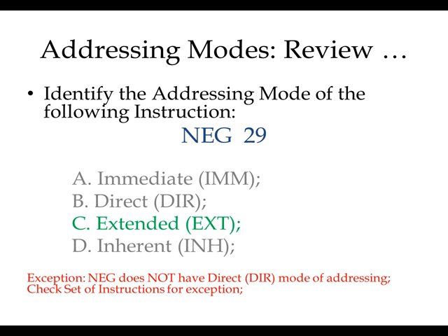Remember, according to the rules we know, it looks like it should be direct, no doubt. But you always want to check with the set of instructions. Check the NEG there. It should be in alphabetic order. Did you find NEG? Look at how many modes are available there. What modes do you have? Extended and indirect. So it does not have the direct mode.